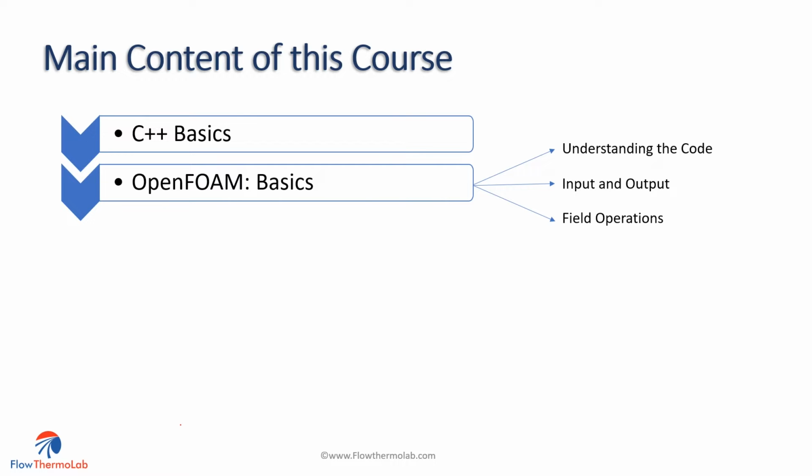Next, moving on to concepts such as input and output, understanding how the mesh works in OpenFOAM, and learning about basic field operations, so how we can manipulate our pressure and velocity fields, for example. And finally, within this section, we'll introduce the concept of debugging within OpenFOAM, and how we can really use all of the tools available to us to develop our code.